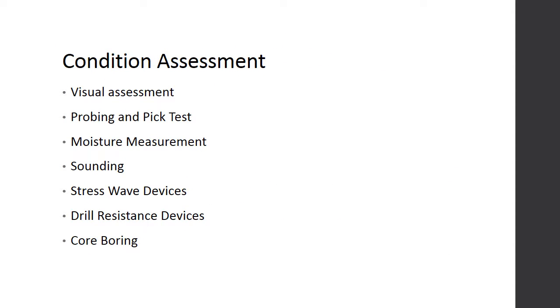A number of tools exist to assist the inspector with the diagnosis of deterioration and needed maintenance. The tools vary considerably in the amount of experience required for reliable interpretation, accuracy in pinpointing a problem, ease of use, and cost. No single test should be relied upon for inspection of timber bridge components. Rather, a standard set of tools should be used by inspectors to ensure conformity in inspections and consistency between inspectors.